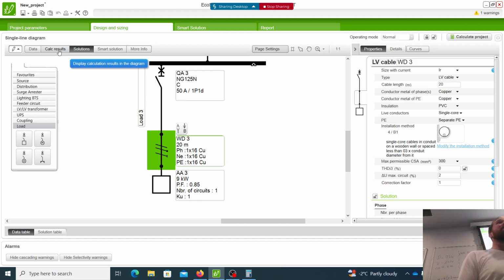It looks painful, but if it's in the exam, you'll be given it. Yeah, in the old standards, it was a table of millivolts per amp per meter for different cables, and that was a case of multiplying it by the distance and the current. I'm not saying this is the better way or the right way. I'm saying this is the way, and that's all I have to say.